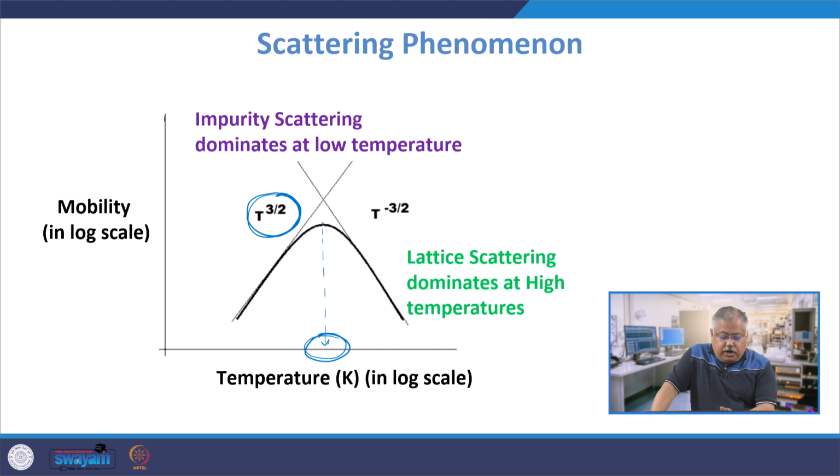But let us come to the point of why there is an increase in the value of mobility at relatively low temperature. I had also told you earlier that primarily it is the scattering mechanism. Primarily, when the electrons are moving through a lattice, because they scatter off the lattice points, their velocity falls and therefore their mobility falls as you go on increasing the scattering. So, the higher the scattering, the more reduced is the mobility. If there is no scattering, which is basically ballistic transport, then the mobility shoots up extraordinarily high.